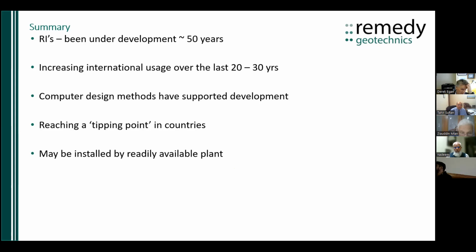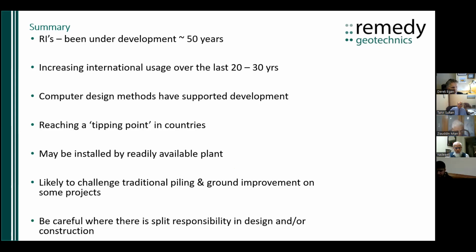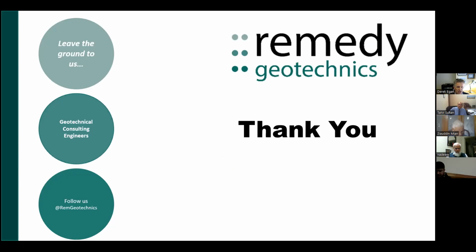They can be installed by readily available plant if you've got piling rigs or ground improvement rigs. You've got the kit to do it. You may need some tooling, but that's relatively easily obtainable. And the system is challenging traditional piling and ground improvement on some projects, without a doubt. So it is certainly an emerging technology. But do be careful again where there is split responsibility in design and/or construction. Okay, so that is that.